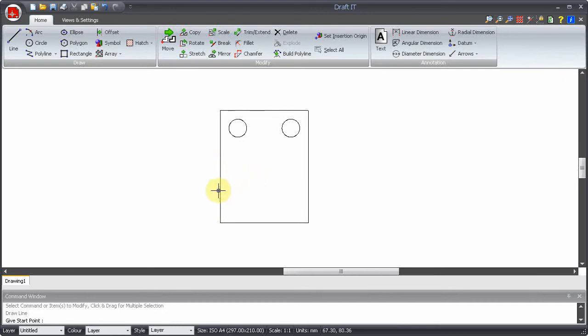For example, position the cursor on a line and press the M key to find the midpoint of the entity, or E to find the nearest endpoint. You can see here, if we move the cursor past the middle point of the line and press E again, the snap jumps to the other end. The snap isn't selected until you click, just as it is normally. So here we will pick the midpoint by pressing M and then click the left mouse button.